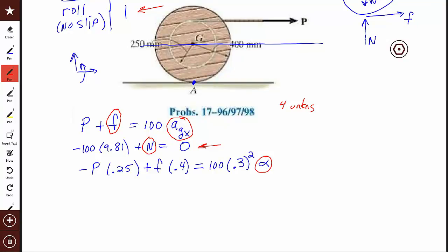What you do is you come in here and you say, okay, let's look at the kinds of unknowns that I have, and what I'm interested in is how many motion unknowns do I have. So let's count them, right? So this one, A, is a motion unknown, and alpha is a motion unknown. So I have 2 motions that are unknown.